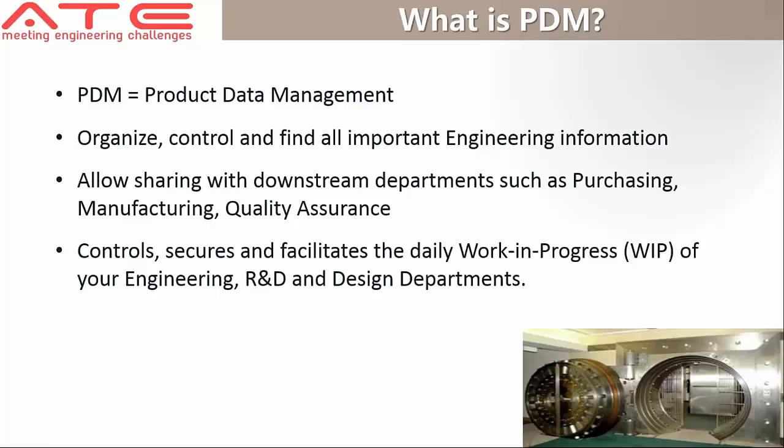So what is PDM? PDM is basically called Product Data Management tool, where you can organize, control, and find all the important engineering information, and allow sharing of data between downstream departments like purchase, manufacturing, and quality assurance to share data like bill of materials and list of documents.